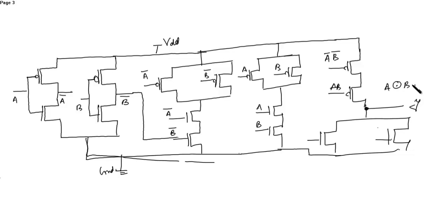So now you can see it's too complicated to draw the twisted schematic of this and then the layout. So what we will do, we'll draw the layout from the schematic by using the transmission gate. So let's see in what way you can reduce this number of PMOS and NMOS. This can be done by drawing the schematic, keeping in mind the truth table of the XNOR gate. So you can write it as schematic from truth table.